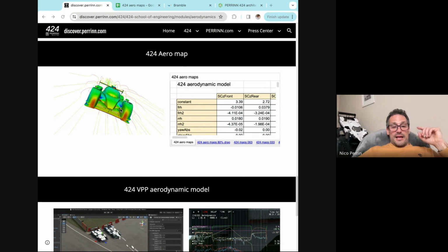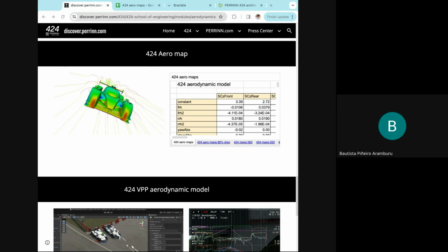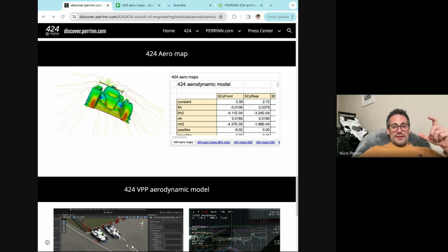And I believe on the Pescarolo we had two problems. First of all, that sealing near the suspension didn't work, and also that aggressive flow, which was attached in CFD, the flow was following. I believe on the Pescarolo it was not, and it was shooting up. So that's another mistake I did at the time, because in CFD sometimes you will not separate the flow as quickly as in the real world, or it can be the opposite, but I've seen that.